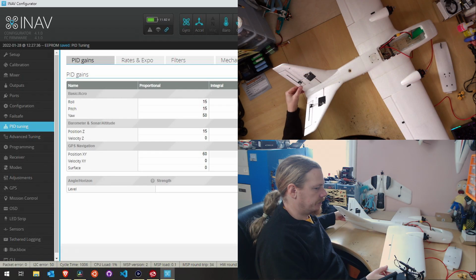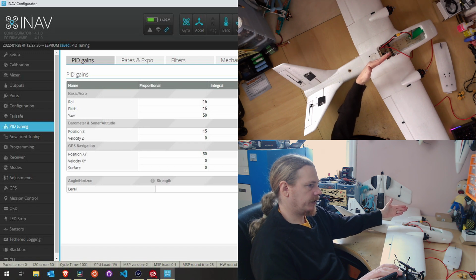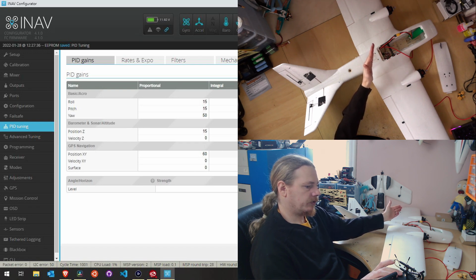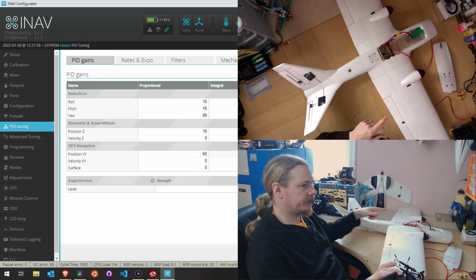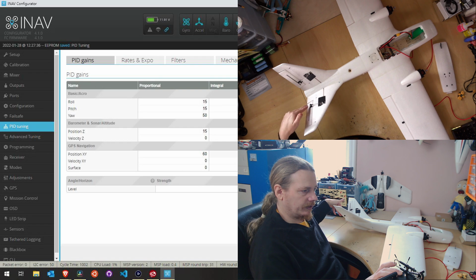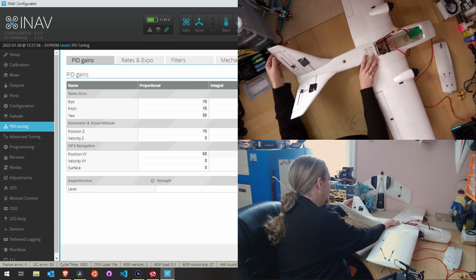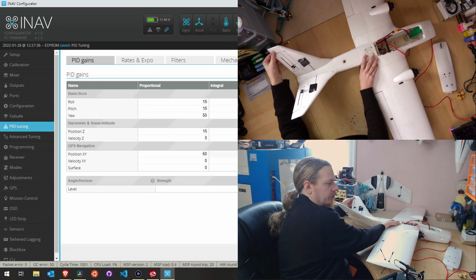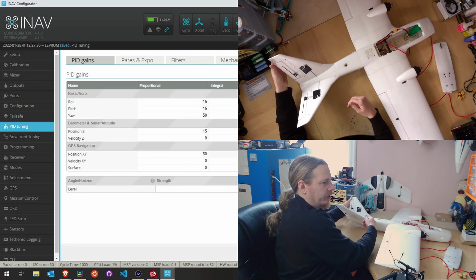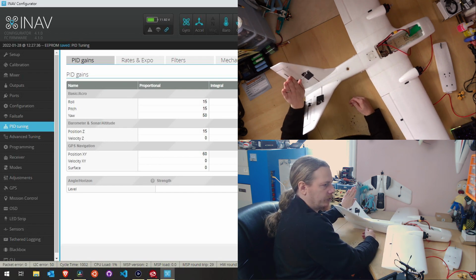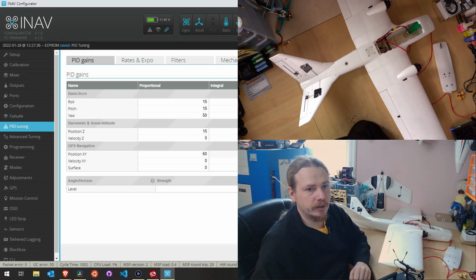So what we want it to do is, if the aircraft is rotating to the left, we want to obviously yaw to the right. The control surfaces here want to move the opposite direction to the nose, or the same direction as the tail. So if the tail is moving this way, we want both of these to go this way. And the easiest way to do it is to try and feel it. So it's not a visual thing, but if I move it this way, I can feel this pushing up against my thumb. So I know that the stabilization is working the correct way.